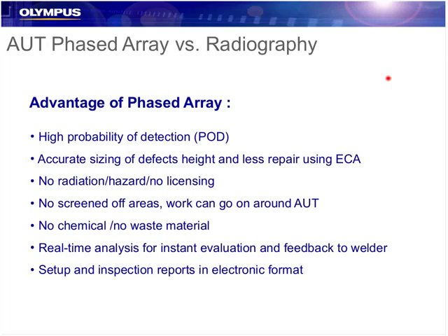We use some colors, some other things. We can quickly tell, yes, the weld is okay. And also if there's a trend in the defects, we don't have to wait for film to be processed and then try to link them together to see if there's a trend, especially with the automatic welder. Something can go wrong. If we're getting the same type of defect happening in the weld, with this type of ultrasonic technique, we're able to instantly tell there's a problem in the automatic welding process and give that feedback to the welder to correct it as soon as possible.